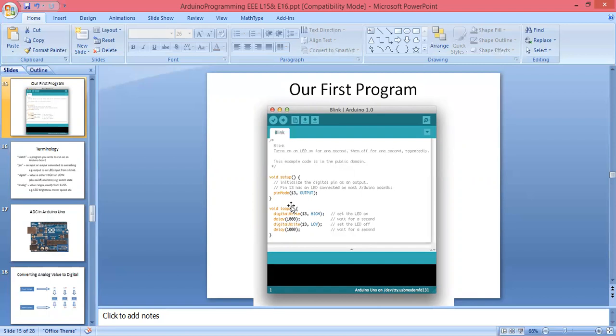So we can make that LED on and off by using the digitalWrite function. So how can we do it? When we are transferring data from our Arduino Uno board to the external LED, we can use the digitalWrite instruction. So while loop में आप क्या करोगे? You will start by using the curly braces in which you will write the statements to make the LED on and to make the LED off. So we can use here digitalWrite, with the first letter of Write capital, in brackets 13 comma HIGH. So that will make your LED glow.